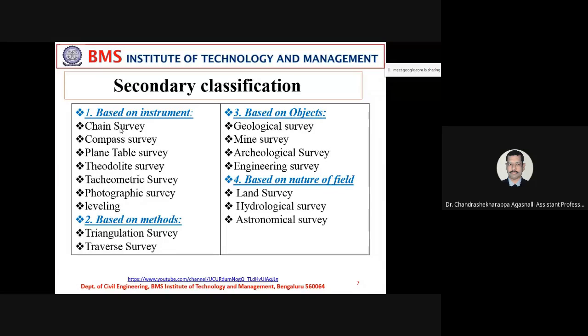At the end of the month, they do the mine survey to assess and estimate the production for this month. By checking the elevation, what it was last month and what it is now, they know how much material they have extracted. That's one type of survey.